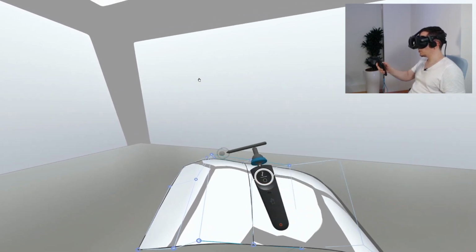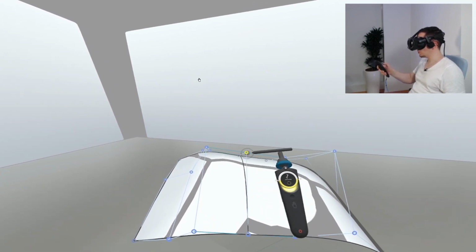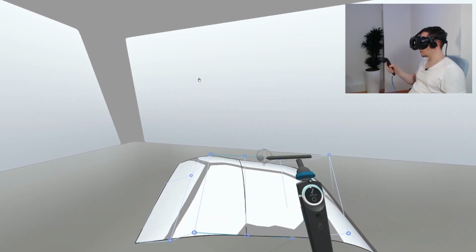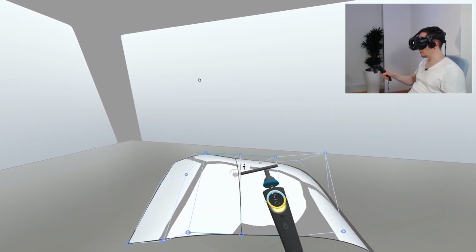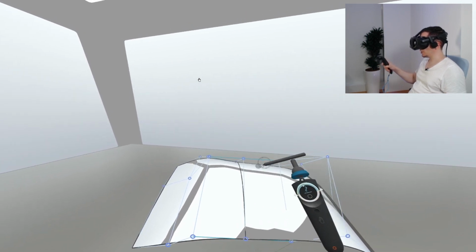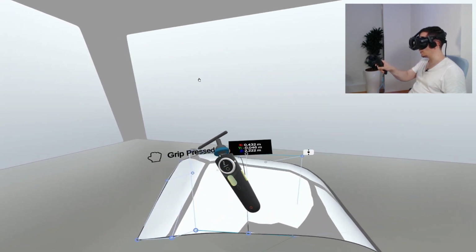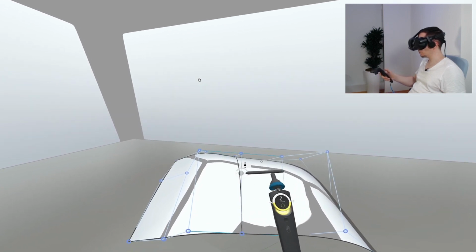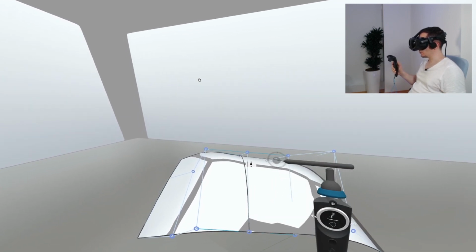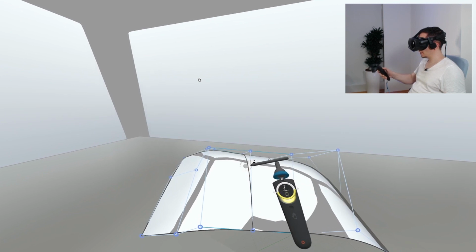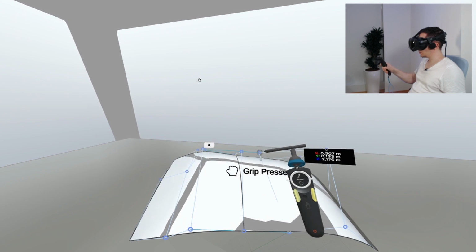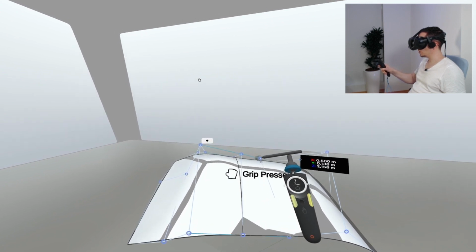You can also here toggle between different continuity modes. So when I hover this central CV that belongs to the curve, you see the icon that indicates that this connection is always symmetrical. So when I change this length, the other one changes as well. I can toggle these modes like for the curve tool when I hover the connecting curve and press the mode button again. So you see now it's not symmetrical anymore, it's still connected.